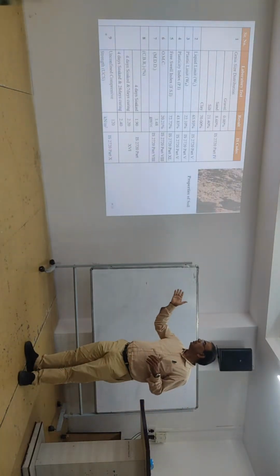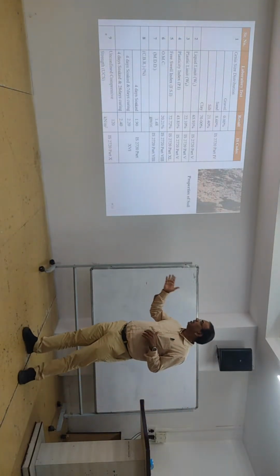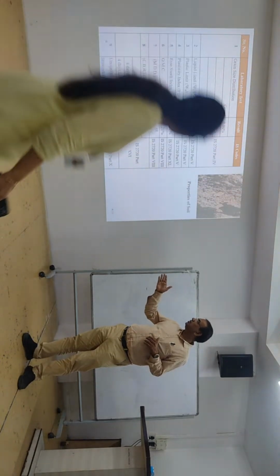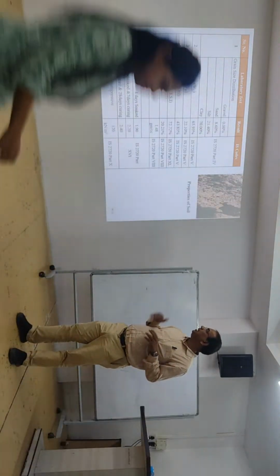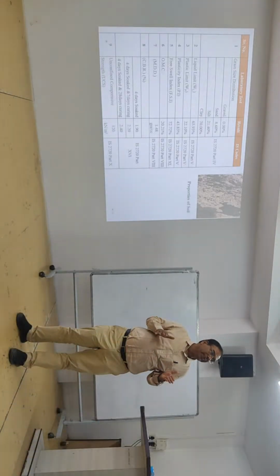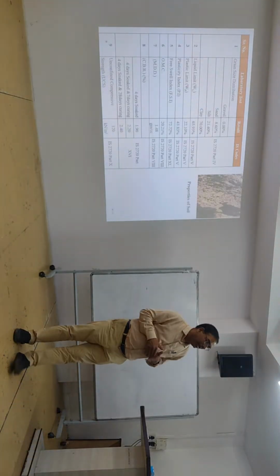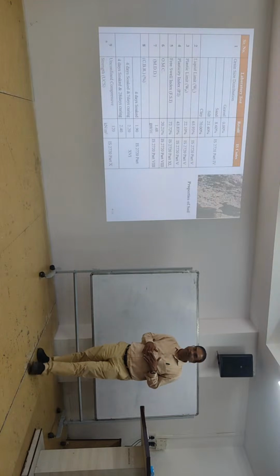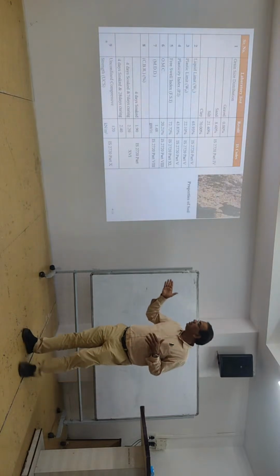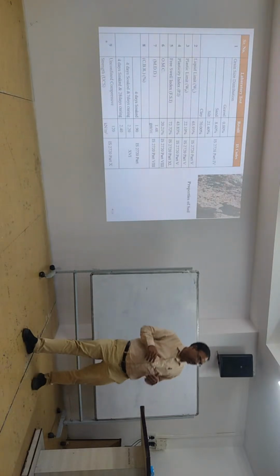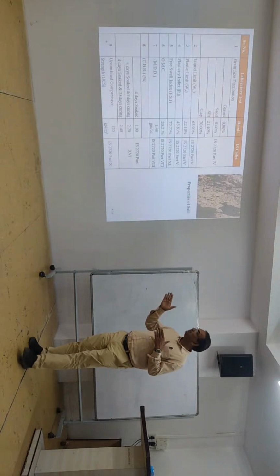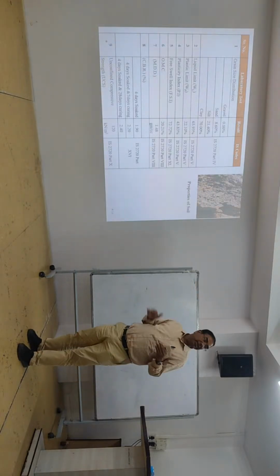CBR is very low, you can say 7 days, we can say 1.9. So almost 2 CBR we are having. But for road construction we require 8 to 10% CBR. So this value is only 2% CBR. For road construction required 10 CBR. So this is soil, so we need improvement.